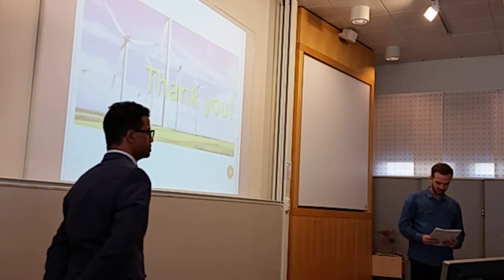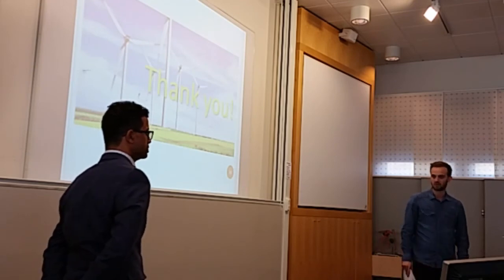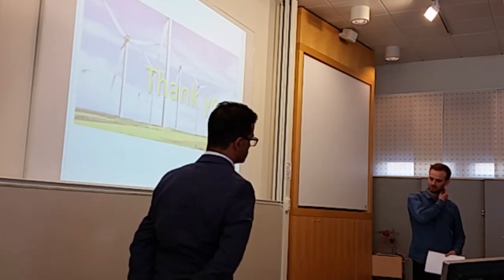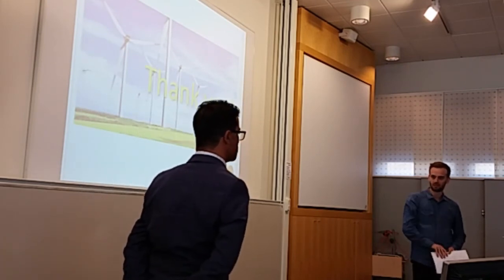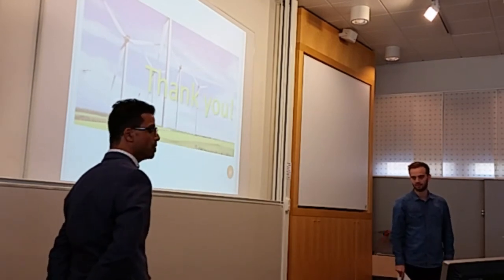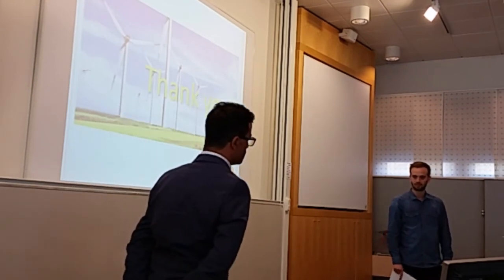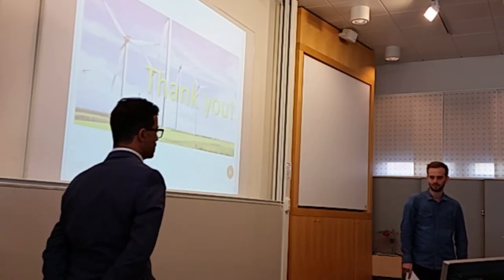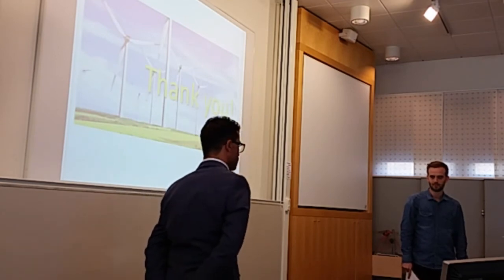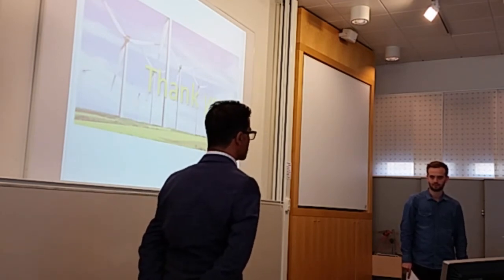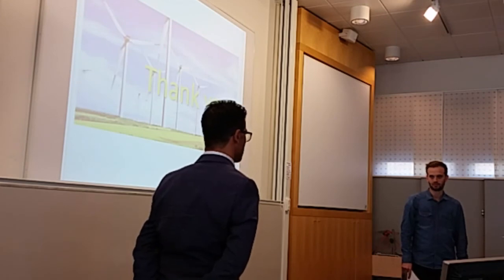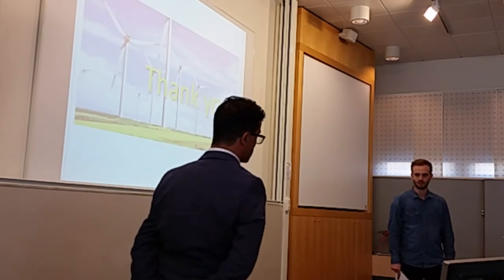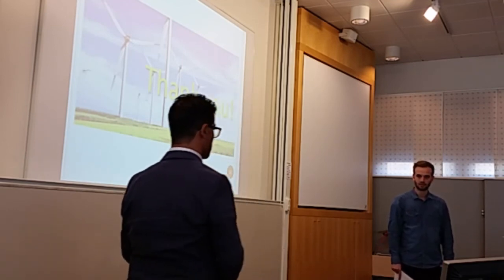I also have a question about the hydraulic system. Have you calculated the energy needed to raise the hub height by 50%? Or did you just... It depends on the weight of the nacelle. Here in my master thesis, I take some model numbers, and the total nacelle weight is approximately 100 tons. It depends on what's in the nacelle, which system we'll be using. For example, if we use a doubly-fed generator or a direct drive, the weight is different from one model to another.